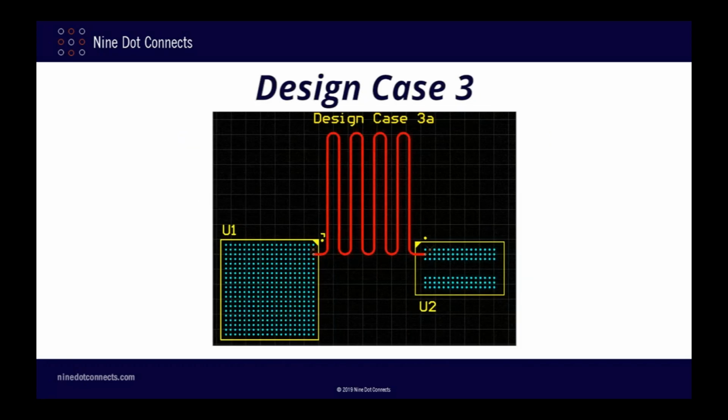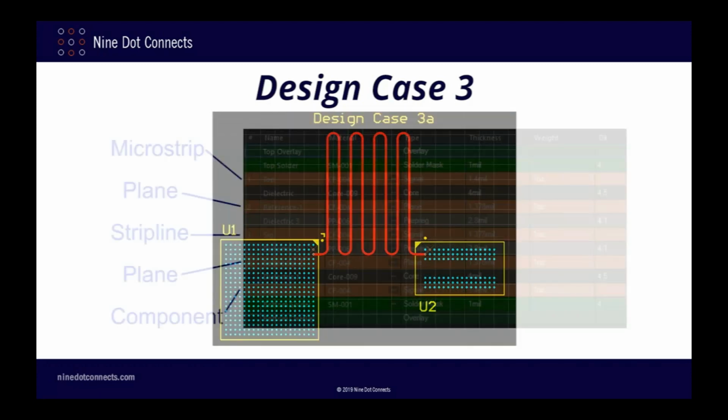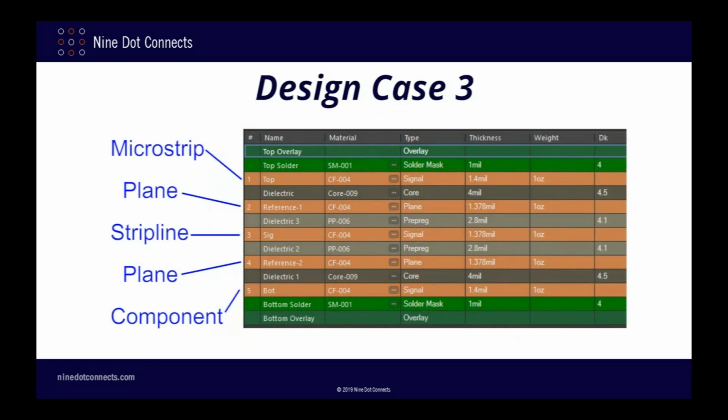Here's the first layout I'll use in order to examine the various aspects of microstrips and strip lines. Since we're mainly interested in looking at the overall timing aspects of the signals, I've created a design that has a long serpentine trace in order to give us some length to play with. In addition, I've expanded upon my 4-layer stackup, adding another signal layer in between the two reference planes. While this ends up giving me an unrealistic 5-layer board, it will let me more easily compare and contrast just the effects caused by changing the routing layers.